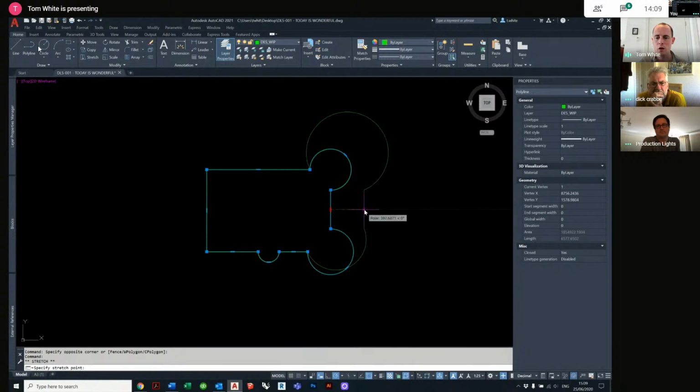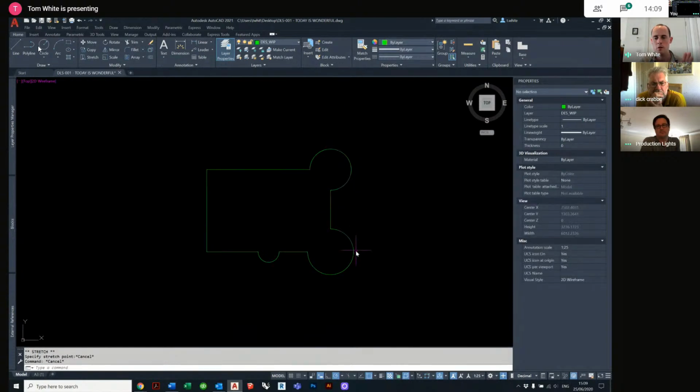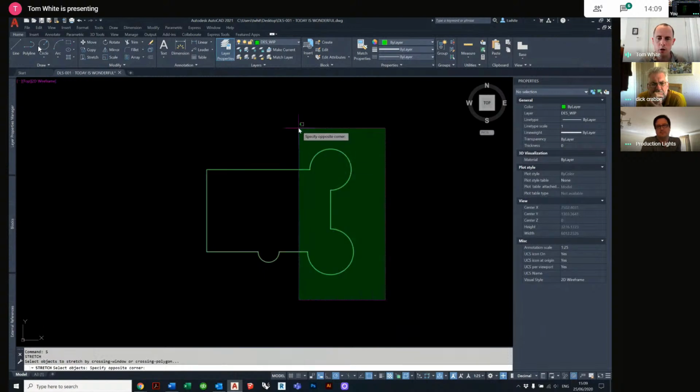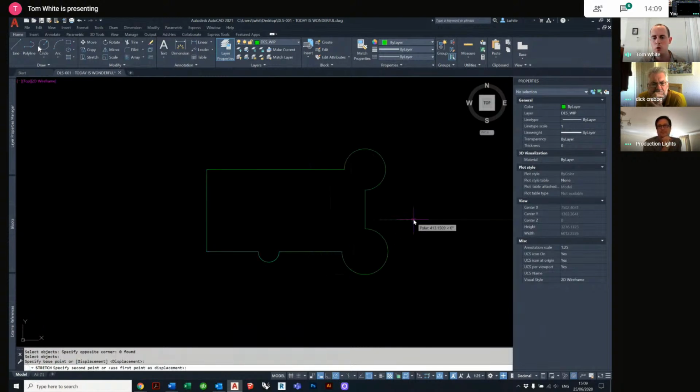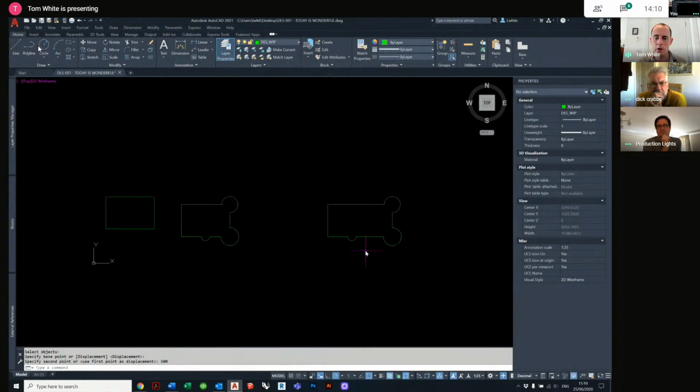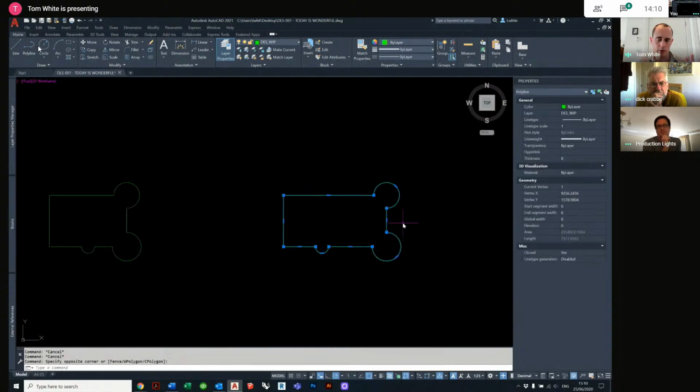because I could stretch it, but it would deform it slightly. Often the stretch command is to keep what you've drawn, but just stretch it away from one another. So in this circumstance, I'm going to use the stretch command over everything I desire to stretch to the right-hand side. I say yes, I click a base point, and I select 500 millimeters. So that's the scenario where the stretch of a polyline can be used in two different circumstances.